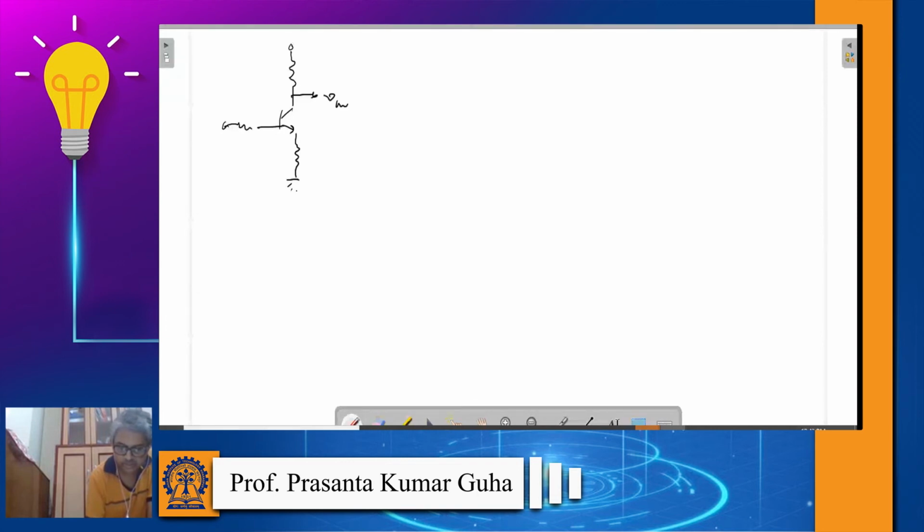So what we are considering now is that I have the same circuit, the only difference is now I have a resistance in series with this input signal, which in reality will be the case. We haven't considered that before because we had a much more simplified version of that common emitter discussion. So if we assume that Vin has a resistance RB, then you see the gain will drop.